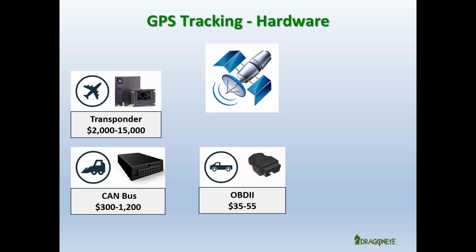This field is flooded with vendors, and the differences in hardware costs can normally be traced back directly to the quality of the GPS chip. Location accuracy will typically be around 40 feet, with an update rate of 1 minute or higher, depending on the associated communication plan. These systems are usually found employed in situations where there is a need for location information that is general in vicinity, and the communications flow is one way with no in-cab location awareness of other assets in the system.